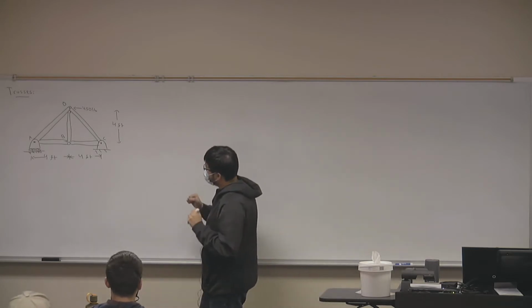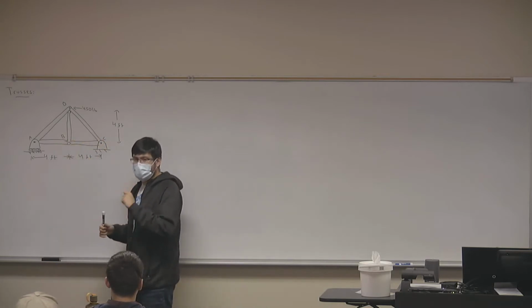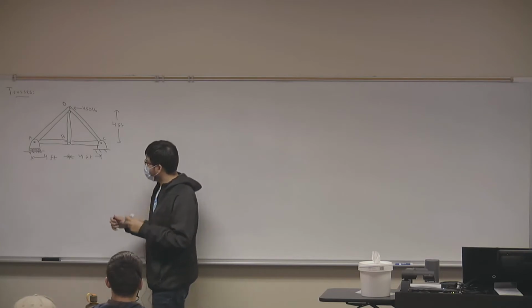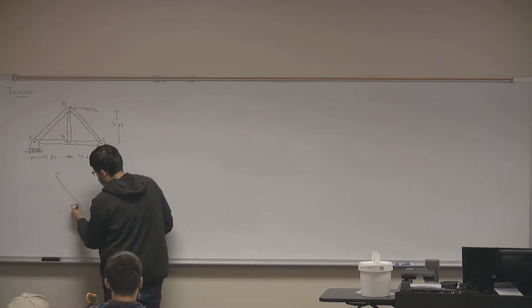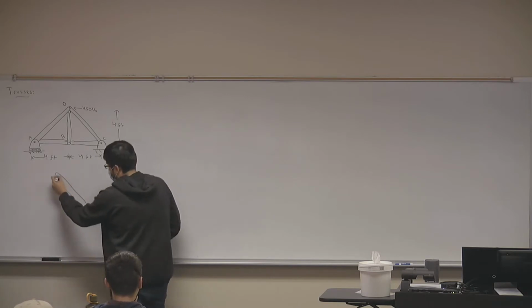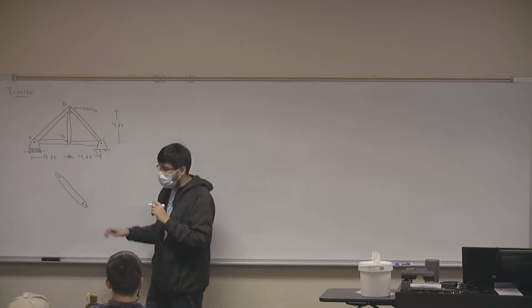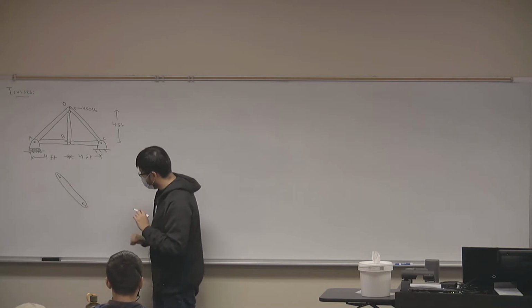So what I want is to find the forces on each of this truss, and each truss in this structure. But I'm going to give you some hints. Let's say I look at a truss individually, a truss DC, just DC individually. I have my truss, I have my two hinges, and the truss will experience either a compressive force or a tension force. And we're looking at this rigid body, right? We're looking at a rigid body right now.